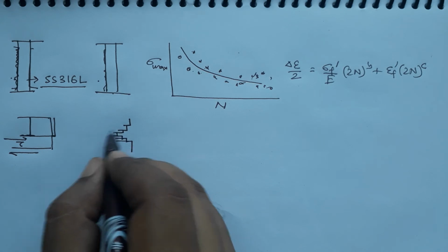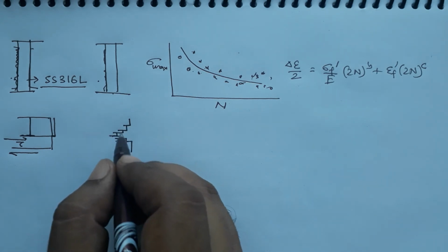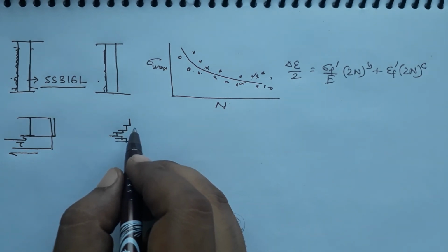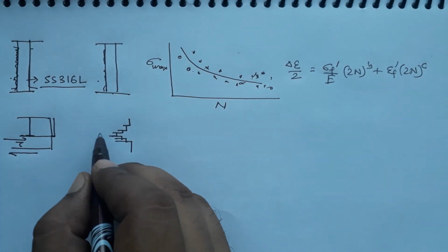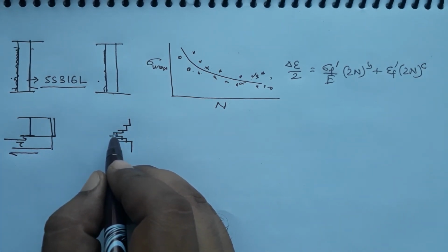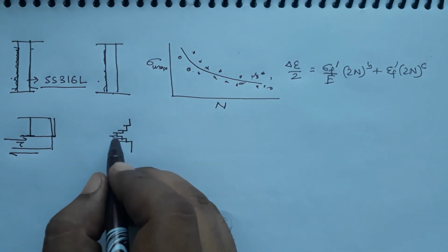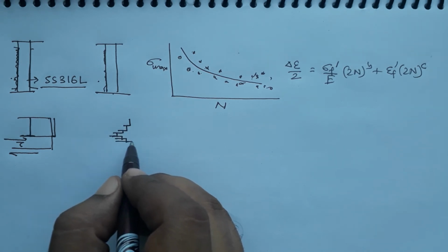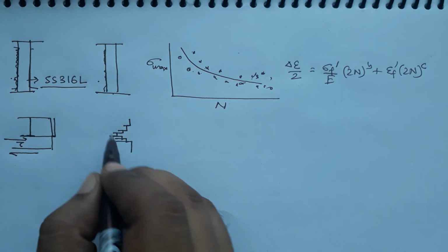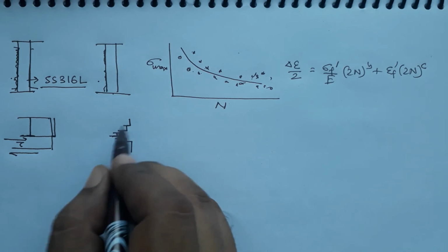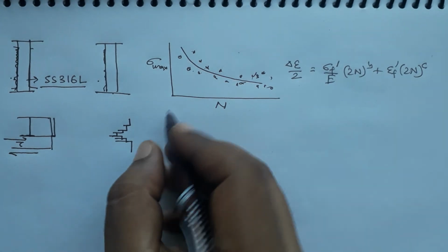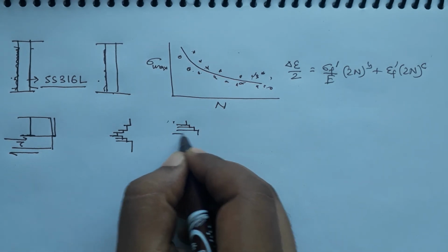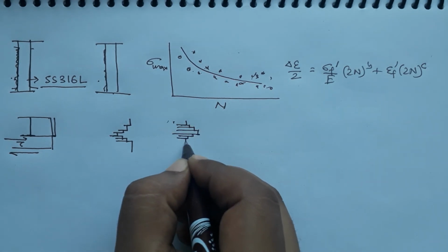These are all different dislocations which have ended up at the surface, or it can be a grain boundary also, and because of the reversal of the stress, some of the dislocations end up not there, but a little smaller in distance. So, you will have a notch kind of geometry or shape formation. The opposite can also happen, so you can have a ridge formation. You can have something like this.